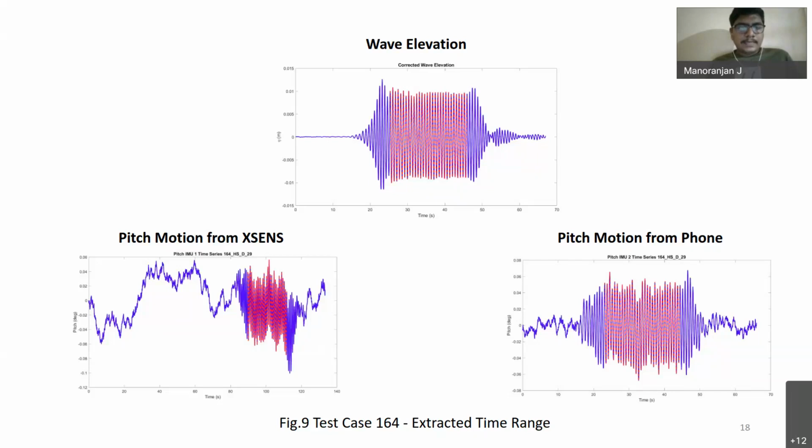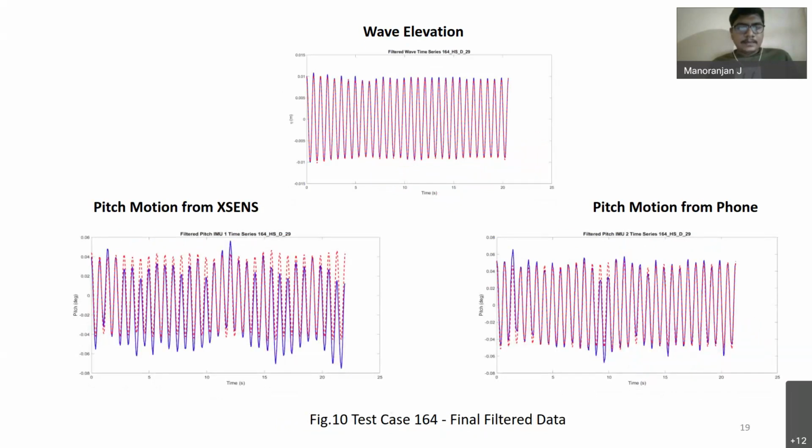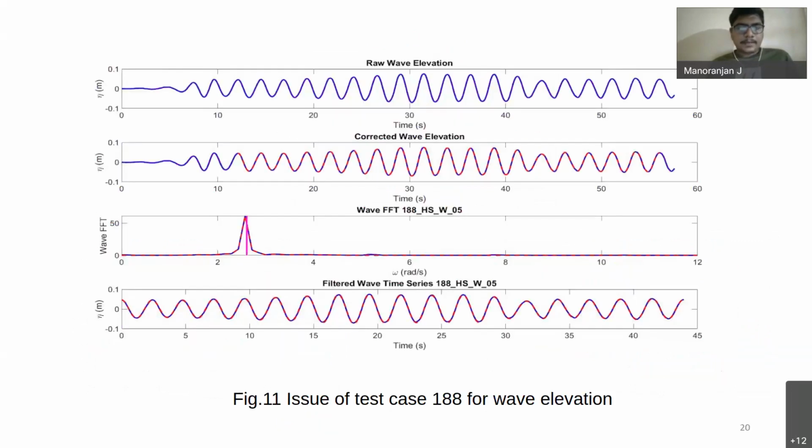Once we extract this time range, for this corresponding time range we again use FFT, similar to what I've told before, filter out the irrelevant frequencies and reconstruct the wave back, and from there we take out the average amplitude. So yeah, that's corresponding to that part.